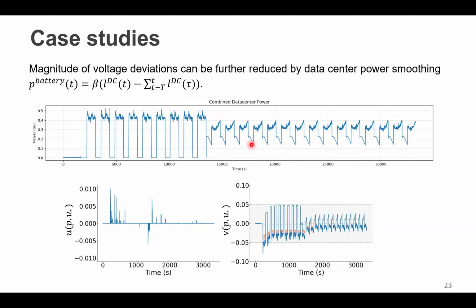Can I ask a basic question? Your relationship for voltage change, does it depend on changes in P, in real power, or does it depend on Q, on reactive power? First, let me check my understanding. Are you meaning that the voltage is determined by the instant? No. Well, there is the decoupling of real and reactive power, right? Oh, right. So maybe on the distribution network, you can still say something about how voltage changes as a function of real power changes.